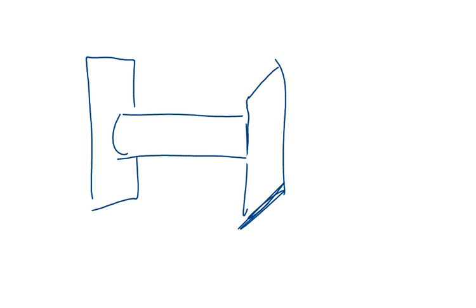You have this rod, you're going to hold it fixed between 2 plates, and then you increase the temperature. What's going to happen here? This rod wants to expand, right? It's going to push against those supports, but those supports are not going to let it expand. So what happens? A force develops, okay? And the forces, of course, result in a stress within this rod, but you end up with reactions at those supports. Right? So you end up with a stress.